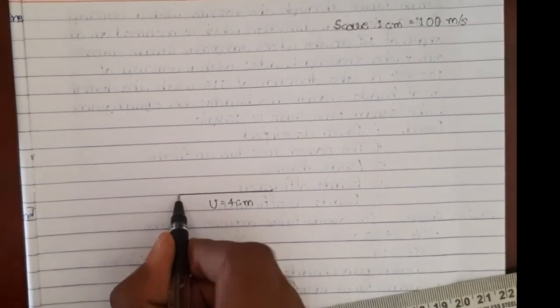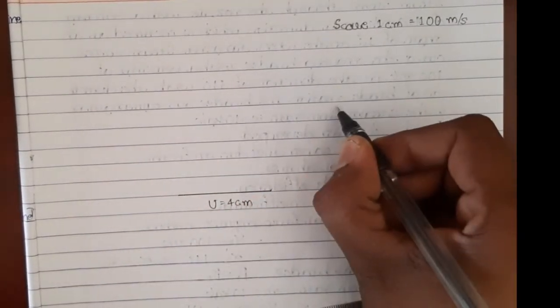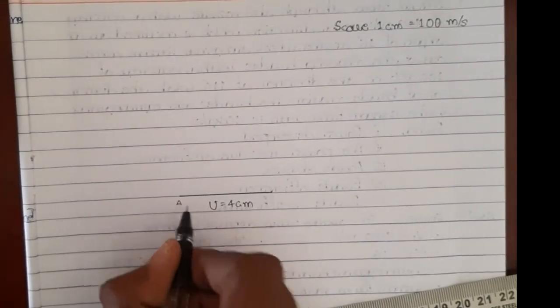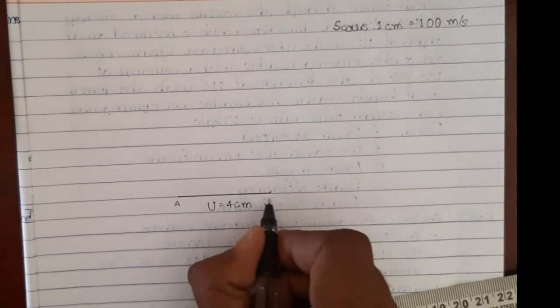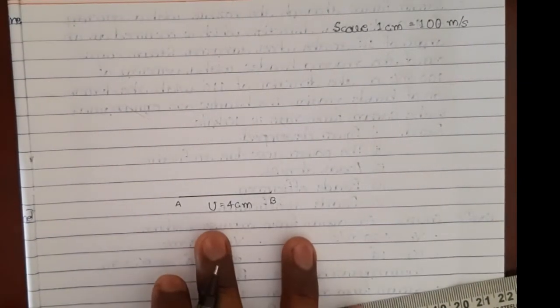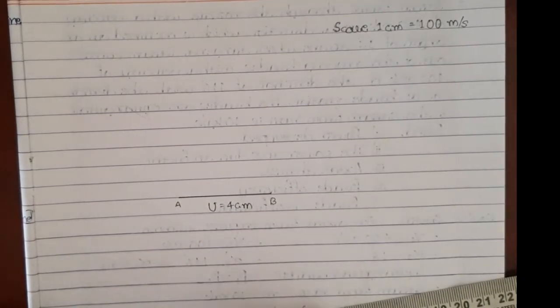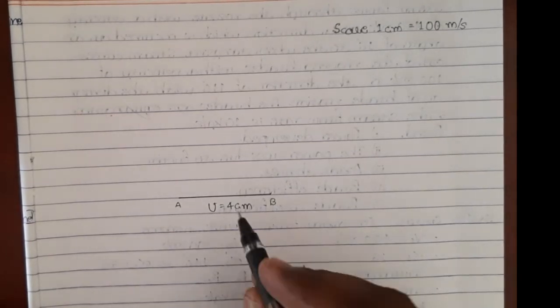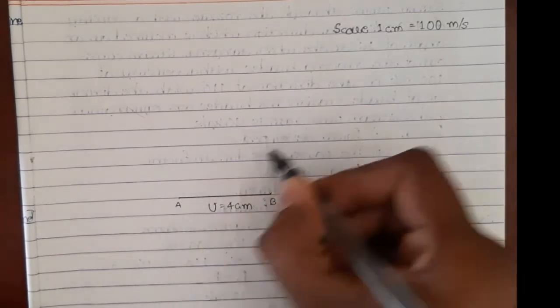Then we also know from this point we will have V1 at an angle alpha 1 and V2 at an angle alpha 2. So from point A we will have alpha 1 and alpha 2 angles, and from point B we will have beta 1 and beta 2 angles, that is VR1 at an angle beta 1 and VR2 at an angle beta 2. So this is the general understanding. If you observe the triangle in the derivation, you will get this. So now what I know is alpha 1 and V1. So I will have to draw V1 at an angle alpha 1 here.